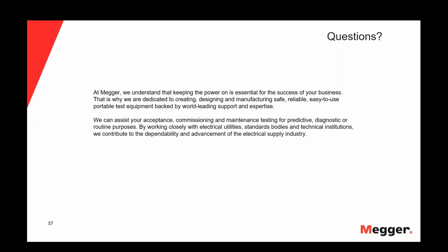Well, probably today, the most utilized test to detect aging conditions is a tan delta test, because it measures the change in dielectric properties of an insulation material, which can be caused by water-tree aging, which is one of them, but it could also be thermal aging, for instance. It could be chemical aging. Whatever breaks up the molecular structure of the XLPE insulation and affects it will be measured by measuring the dielectric losses in the insulation.